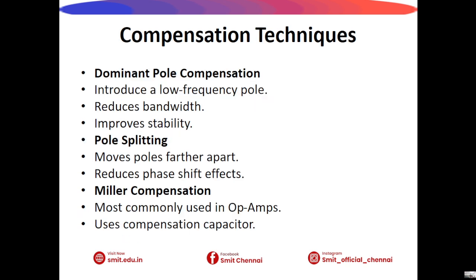Next, we see the compensation techniques. Several compensation techniques are used in practical circuits. Dominant pole compensation introduces a low frequency pole to control the response. Pole splitting separates pole frequencies to reduce interaction. Miller compensation uses a capacitor to create a dominant pole and is widely used in operational amplifiers.